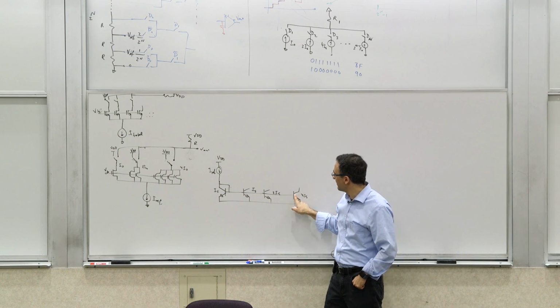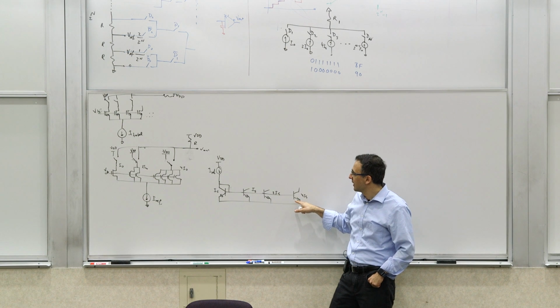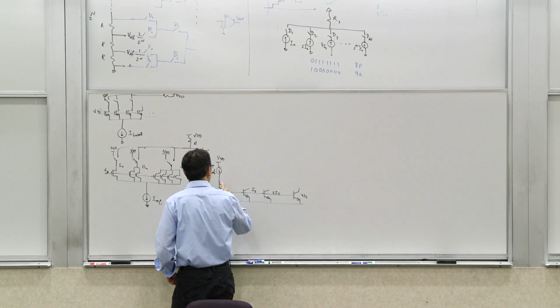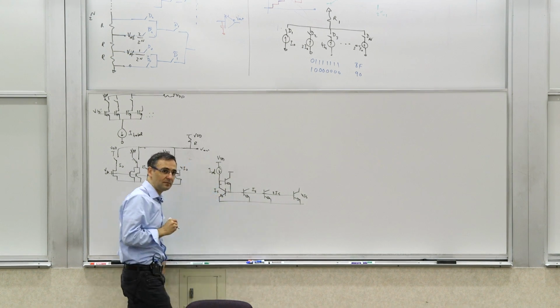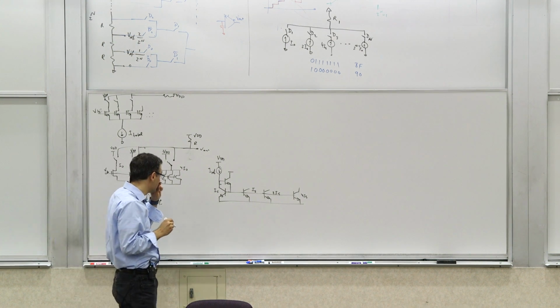Yes, because what happens is that you have a lot of this base current being drawn out of this, and it has to come from here, so it will affect it. So you may need to actually have something like this to buffer the current and get some gain on the base current, so you get a factor of beta advantage there.